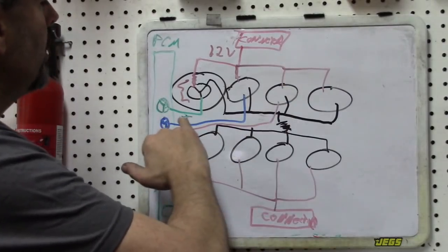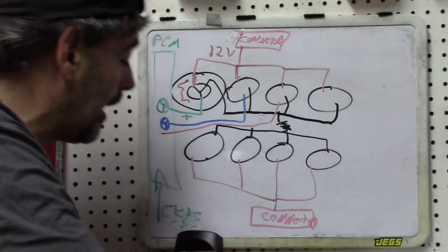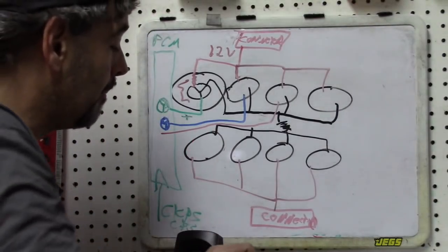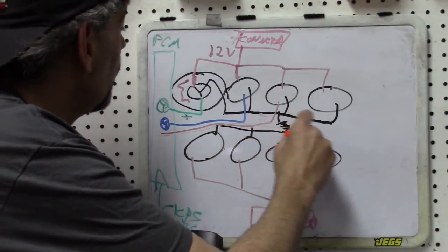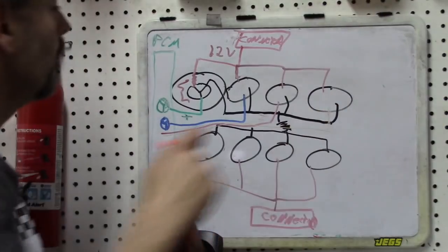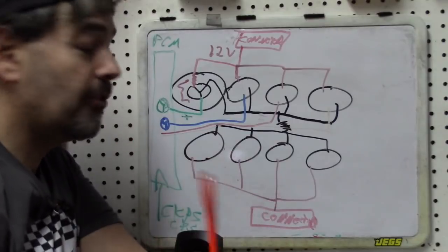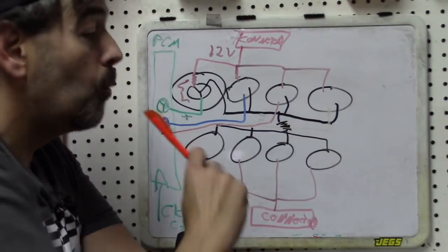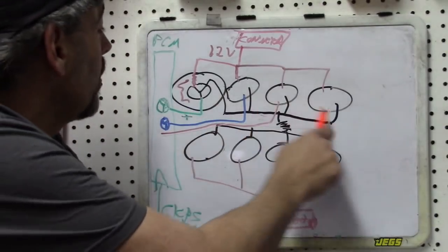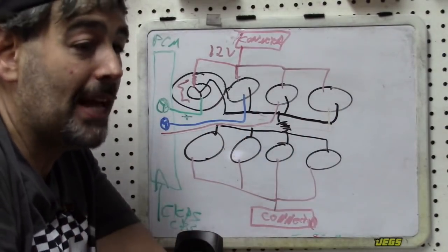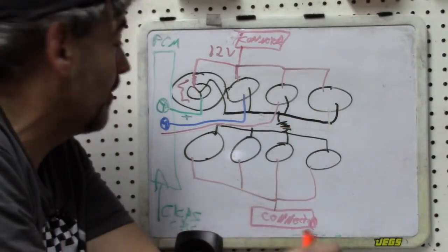As you can imagine, there's going to be on the one connector we looked at, I wish I had another color. You know what? I'm going to just do orange here. Hopefully this is a dry erase marker. I don't know if it is. We're going to do orange right there. Now, we know, because there were 7 wires, we know 4 of them are going to be independent controls. And we've drawn those out. 4 of those wires have to be the independent on-off controls for the transistors in the coils. We know that because we understand the system.